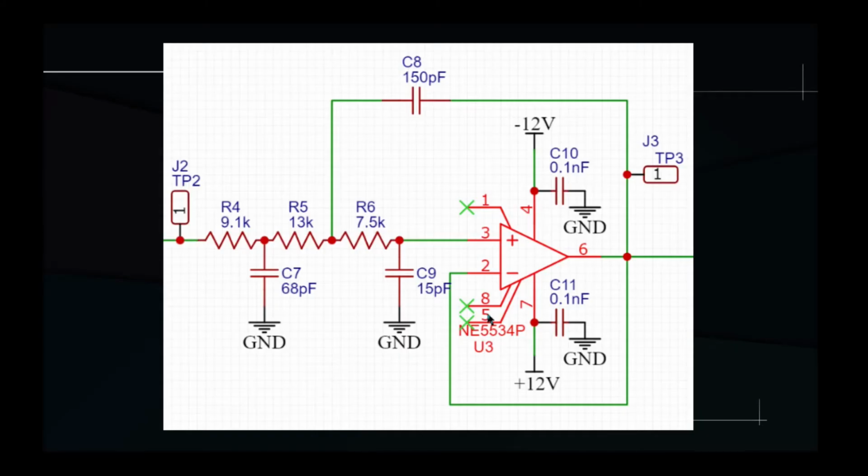Here is the schematic of our filter. It is a relatively simple circuit made out of a single op-amp and a few resistors and capacitors that provide the whole topology of the third-order Sallen-Key low-pass filter. The topology of this filter is based on the topology of the simple first-order low-pass filter, repeated 3 times to obtain the third-order capability. Let's see in more details how this is done.